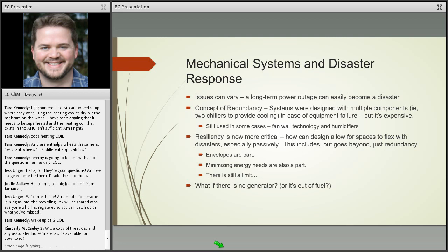It's a very interesting spectrum. The historic structures in Puerto Rico, at least in my experiences, the institutions that I worked with and visited, lost their environmental control, what they had, much more quickly. But over the long term of the power outage, they generally performed much better because they had the capability to allow for natural ventilation and natural airflow, which oftentimes, to a certain degree, mitigated or lessened the degree of the mold outbreak, at least in a collections environment.